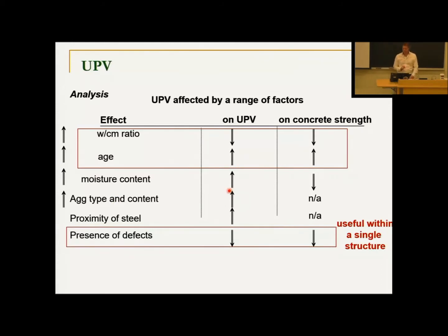And what I want to emphasize with this is that this is another reason you cannot use wave velocity absolutely by itself to predict concrete strength. There are too many uncertainties, it's too weak of a relationship. It should not be done.